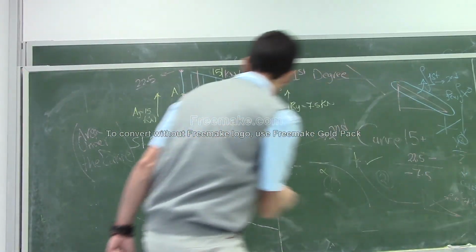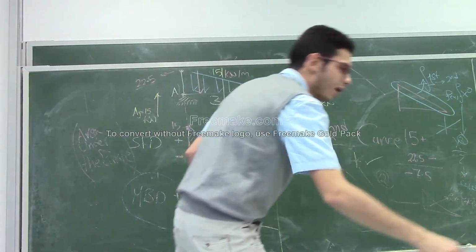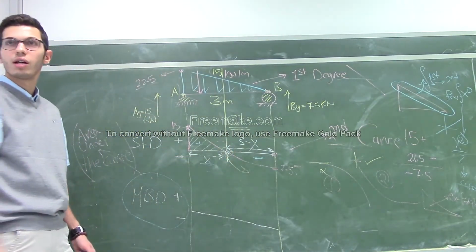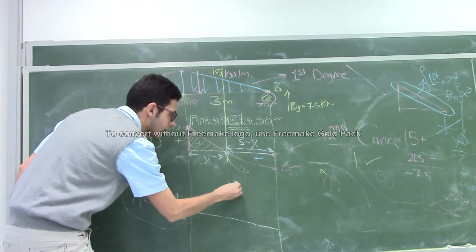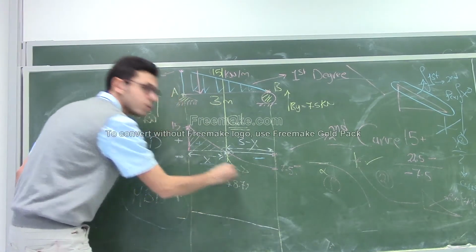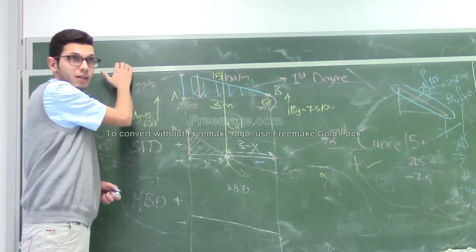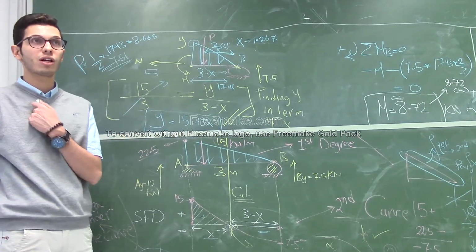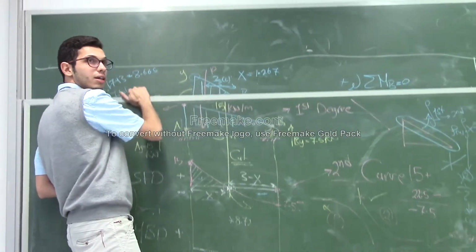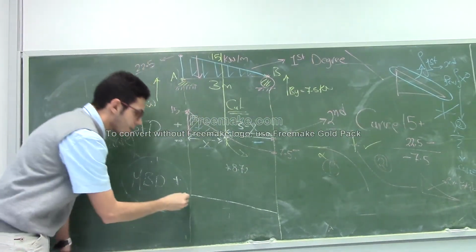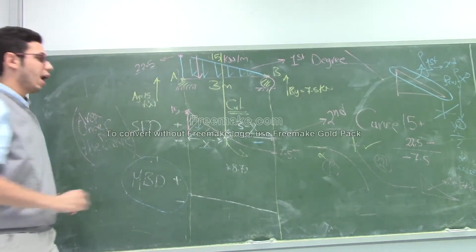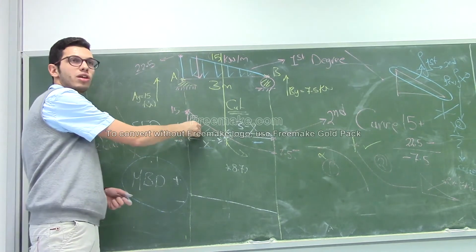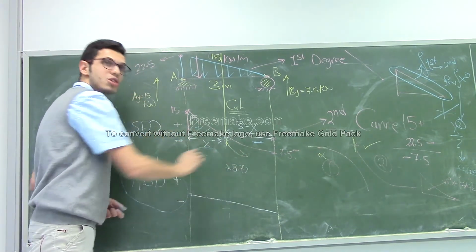So we find the moment here. The moment at this point also, we find it, right? The moment at this point was 8.72, right? And it was a clockwise moment. That means it's a positive moment. According to the table in the past lecture, it was a positive moment, right? So now I'm here at 0, okay? And the moment here is 8.7, okay? And this is a positive area, so I should move from here to this point, right?